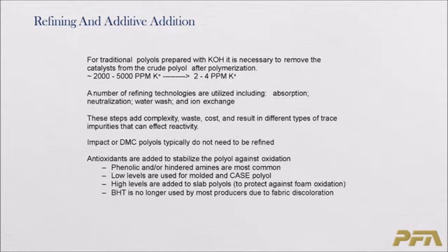So at the last stages of the polyol manufacture, as I mentioned, if it's made by KOH, and a lot of products today still are, you have to remove that potassium down to a few ppm, and there are a lot of different refining techniques for removing that potassium, and many of them will leave behind different sorts of trace impurities, which can often affect reactivity. So people sometimes say, well, I switched one 3,000 molecular weight polyol for another, and they're seeing a reactivity difference. It can also often be due to those impurities that are present in there.